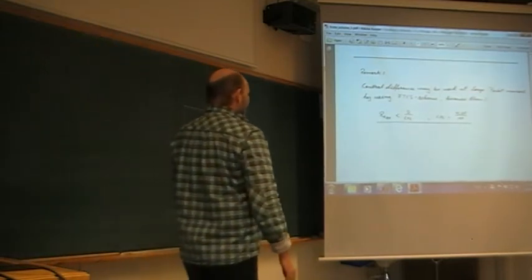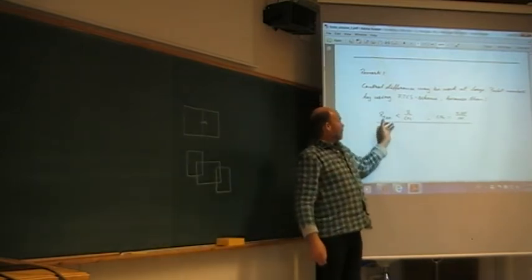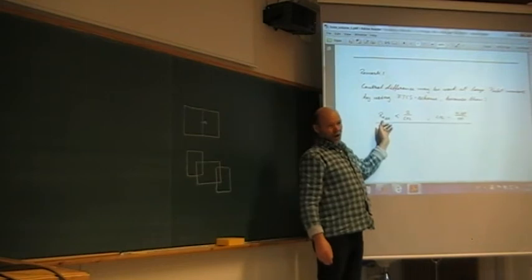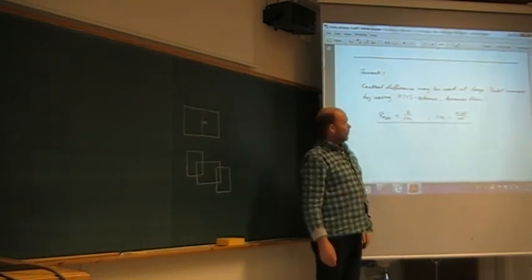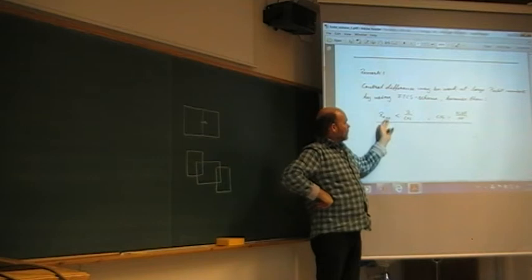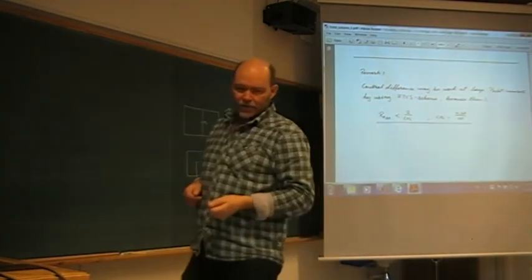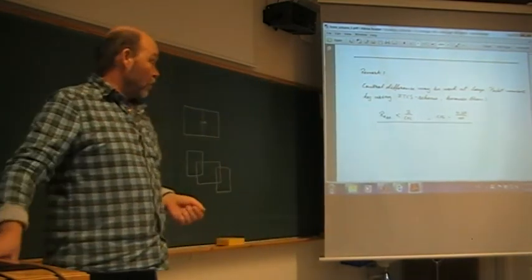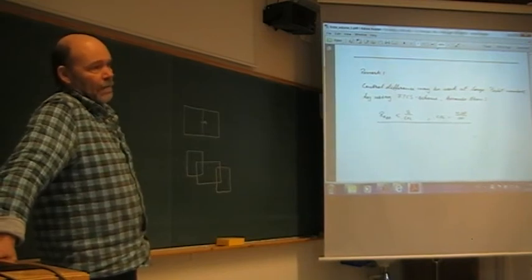Remember, you can survive with cell Reynolds number bigger than 2 if you include time. What we have been looking at so far is steady state. But if you add time, then it can be shown that the cell Reynolds number has to be smaller than 2 divided by the Courant-Friedrichs-Lewy condition, where you have a delta t. So you can play around with very small delta t's and still survive.